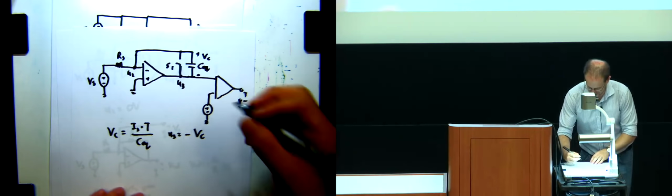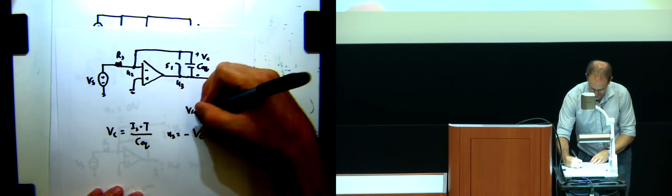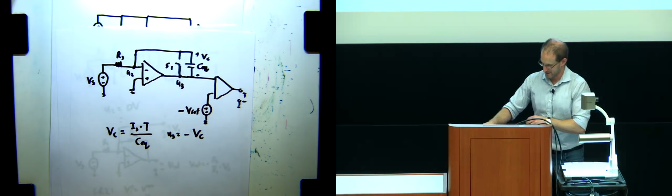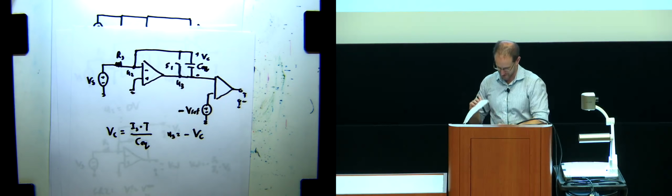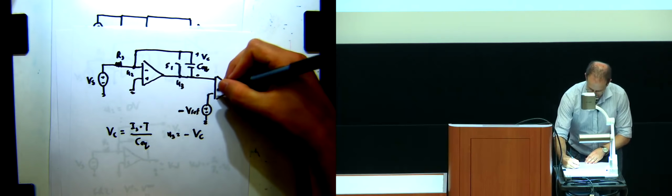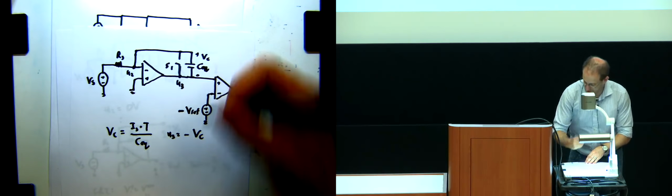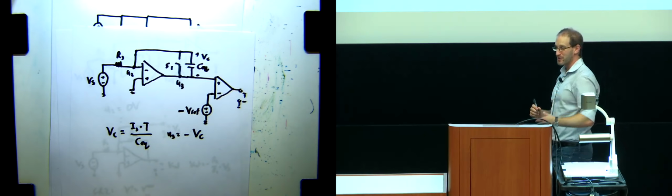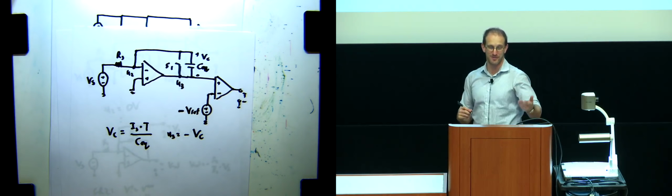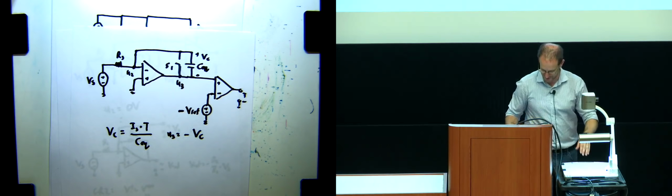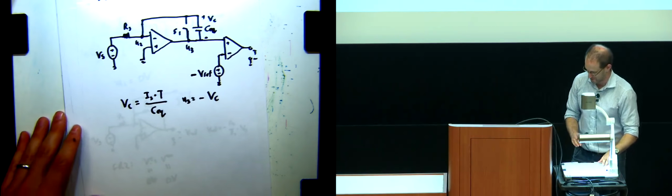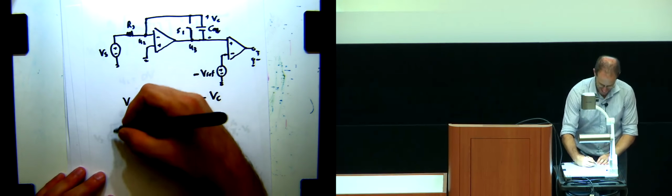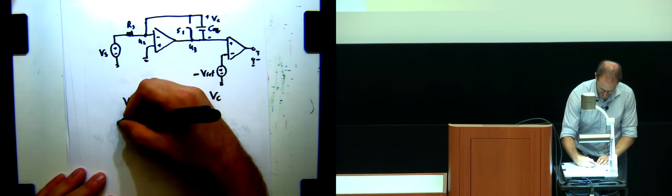Now what we're basically going to say is that instead of comparing against Vref, we'll compare against minus Vref. And now we actually will flip the direction, because we want to check: is the thing lower than minus Vref or higher than minus Vref? I think this will be more clear in a second when I draw the real picture.